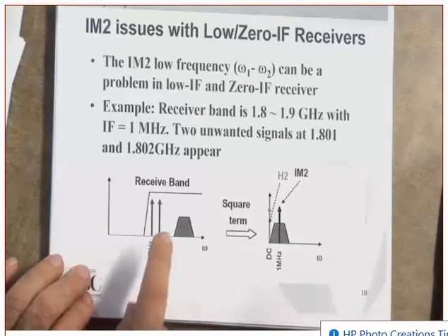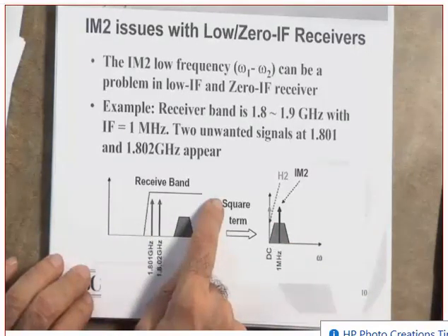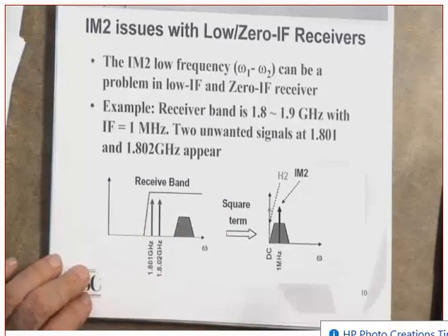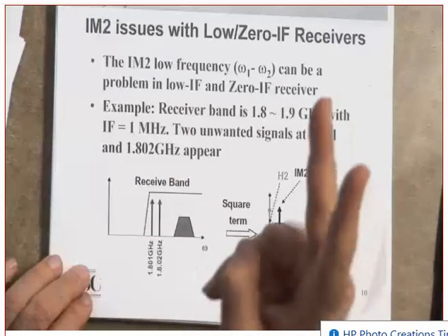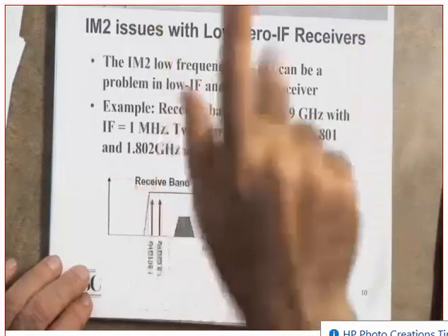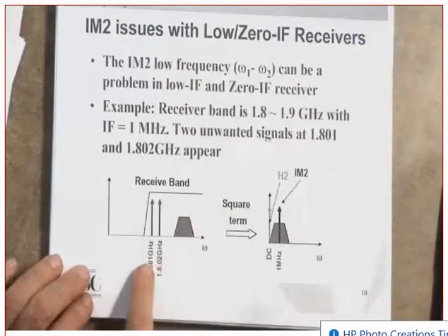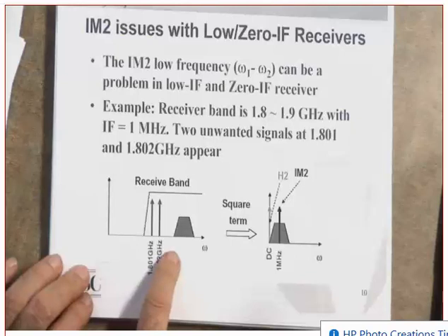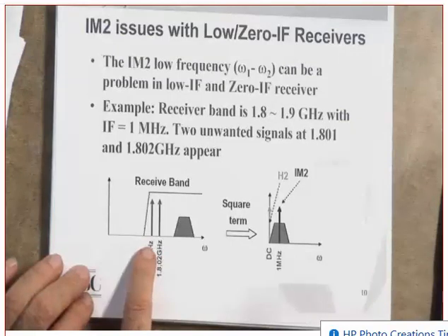These two frequencies are within the band. There is a second order nonlinearity in the chain, which means there is some term that has a square in it. You are going to get the sum, and the difference. Well, the sum causes me a problem.